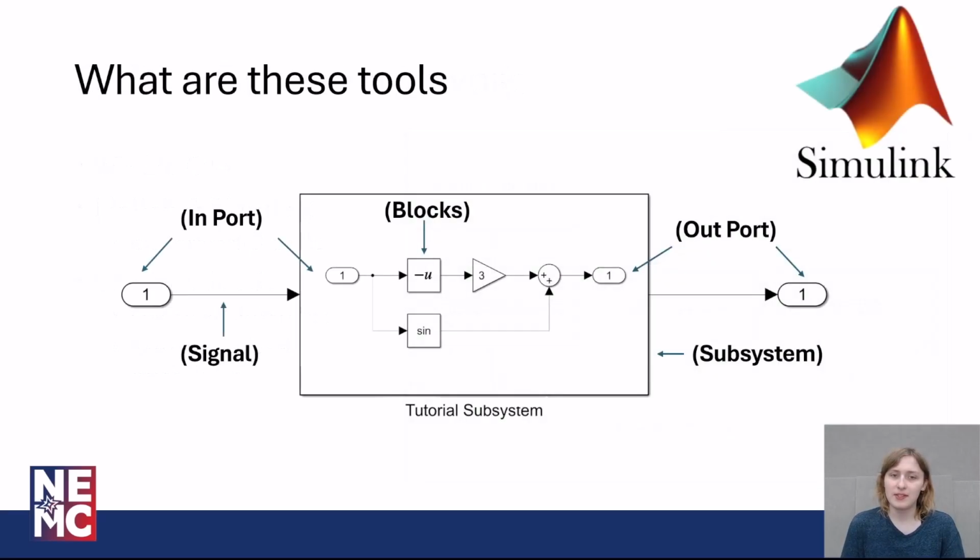So this is a simple little snippet of Simulink code. As you can see here, the subsystem in the middle is basically a function, and the inports act as the arguments, and the outputs act as the return statement. These blocks in the middle edit the data carried by the signals. Basic block coding, but I want to be clear in terms as we get into more complicated topics. All of the programming we do in Simulink is functional programming, though.